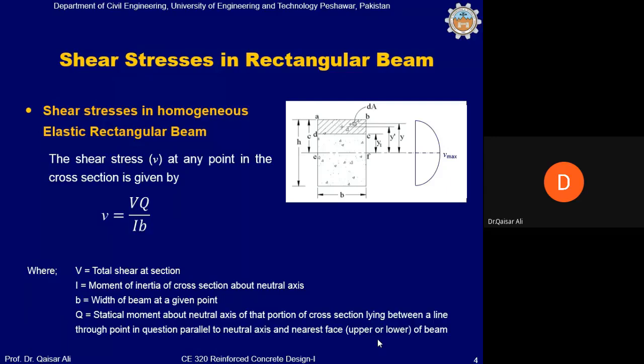exhibits elastic response up to the yield point, so much higher load can be resisted by steel beam within the elastic range as compared to a concrete beam, because concrete beam cracks in the very beginning, at a very early stage as compared to its final stage. So the linear elastic stage in a concrete beam in a very early stage is possible, otherwise it is not possible.